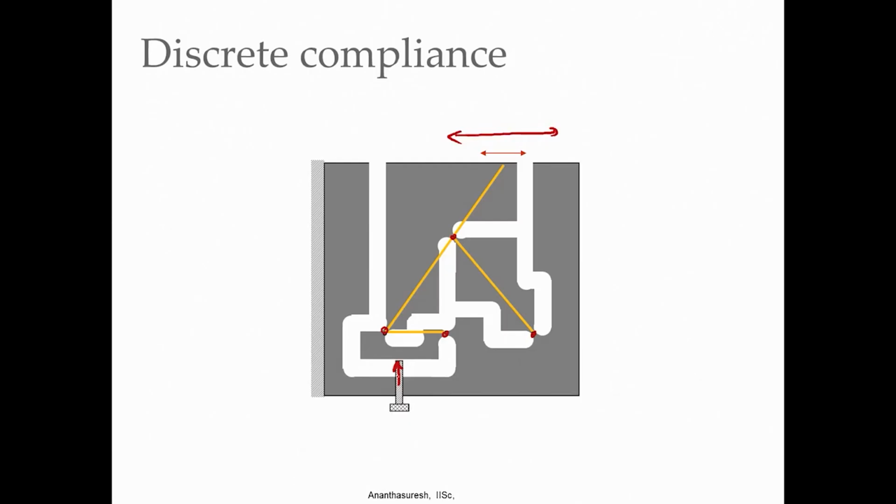It is suitable for precision motions, which are small motions, because these elastic pairs are flexures, as they are called. Okay, they are flexible joints. They are used for very small motions, so that you can get precise motion where resolution, or the smallest motion that you can repeatedly apply, is important. That is the definition of precision mechanisms, where repeatability is important. That means that there should not be any effects from the environment, noise. There could be temperature or friction, backlash, those are not there in compliance anyway, they are certainly not there in flexures. That is why people use them in precision mechanisms.